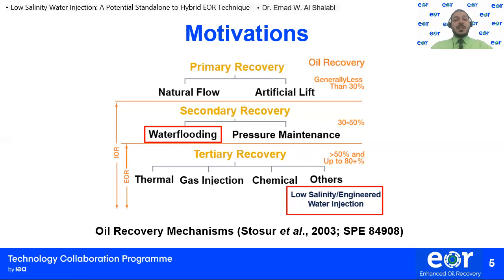And by that, I mean the total dissolved solids in there, TDS, as well as the ionic composition of that water, because this is expected to cause some oil, brine, and rock interactions, and this will be translated into additional oil recovery. And this is, ladies and gentlemen, what we term as low salinity or engineered water injection, which is under the others category of the tertiary recovery or enhanced oil recovery methods.